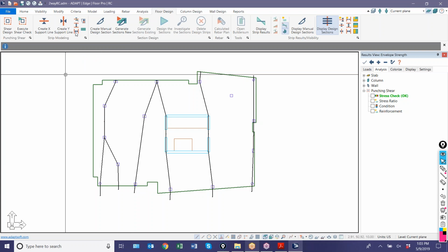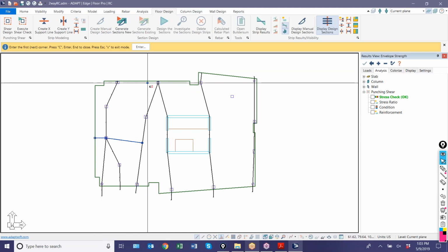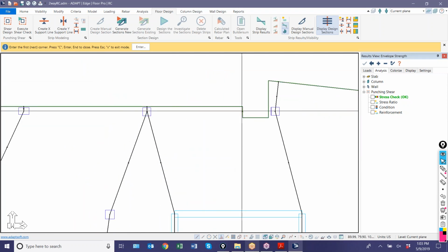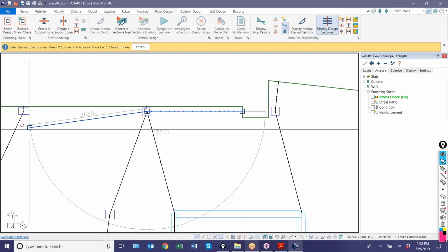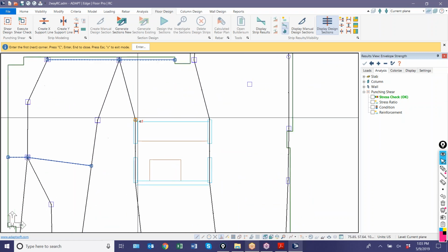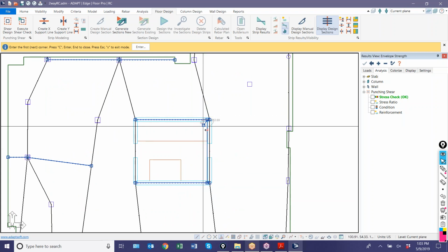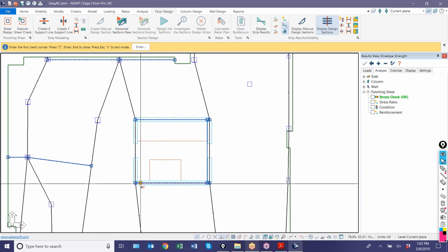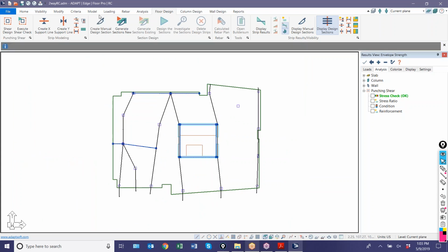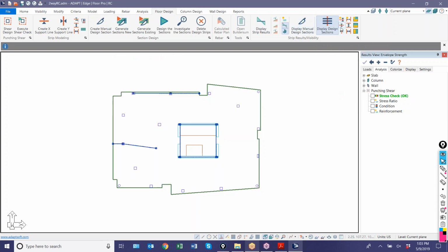We're going to create our splitters for the Y direction. So again, these are placed where we have support lines that discontinue. Like here's another location where that happens. You can always use backspace to undo if needed. And then we're going to again bound out the main core area. Okay, and I'll generate the strips again. So this will generate middle strips and column strips for both directions.